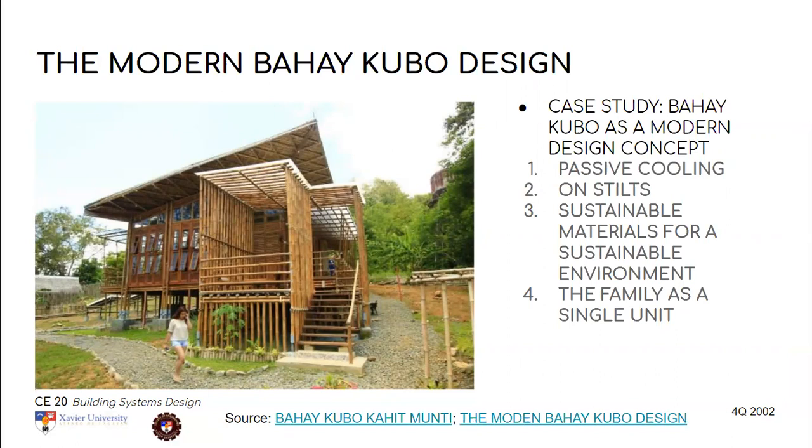The main value of the Bahay Kubo system is that it is passively cooled. It's built on stilts, so there's no need for much excavation. It uses sustainable materials for a sustainable environment. And because the design is for a family, the concept of open spacing, that means that there are fewer walls or division walls inside, is a highly prized item for this design.